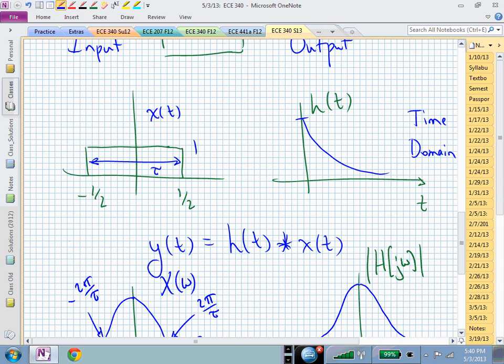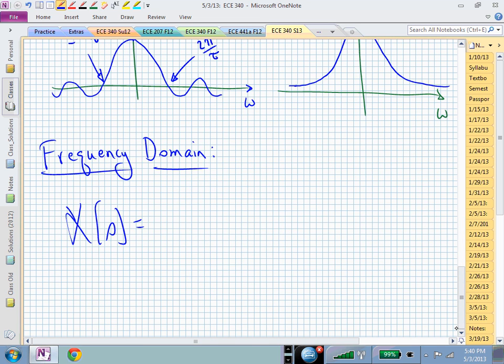Well, that's really what you have. You have a step that's advanced by 1/2 of a unit, and then you turn it off. Meaning in the frequency domain for X of s, you have this step, but if you now shift it in time with this advance, that's like multiplying or scaling by e to the s over 2, where it's now this advance, so it's now 1/2 times s.